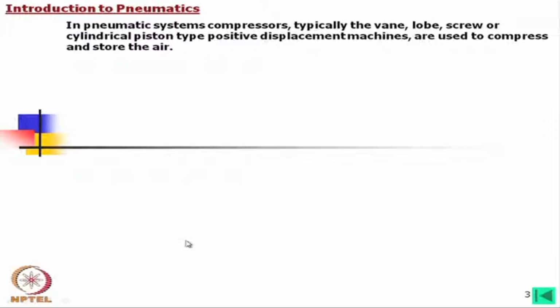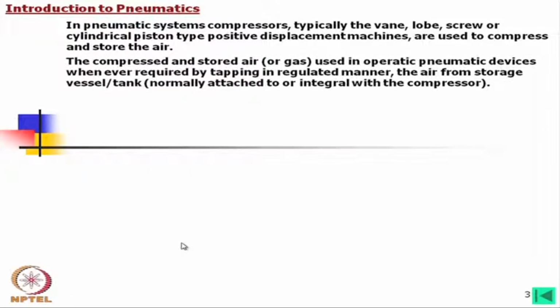In case of oil hydraulics, it is not that. This means that in the conduit, obviously, the volume is equal to that amount of volume, and your positive displacement machine is also delivering the same amount of volume. In case of the air, or gases, it is not.